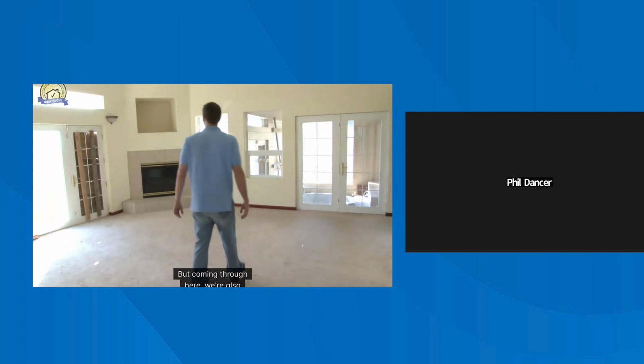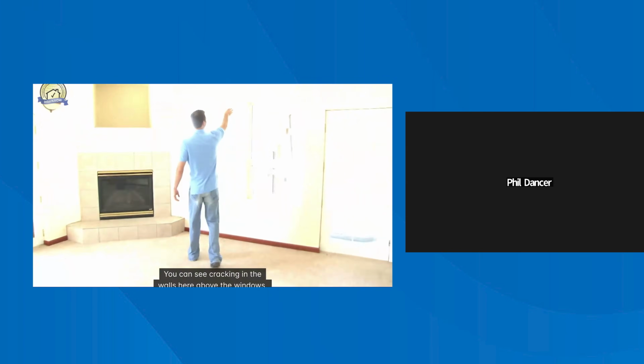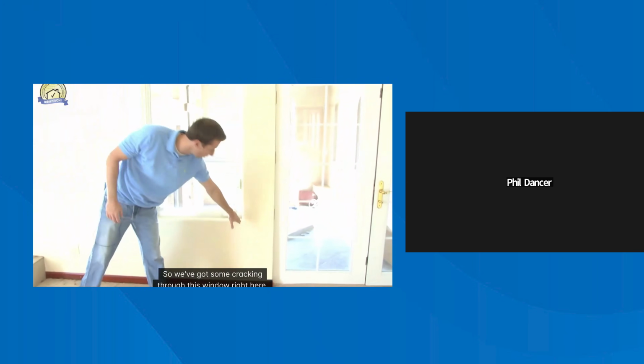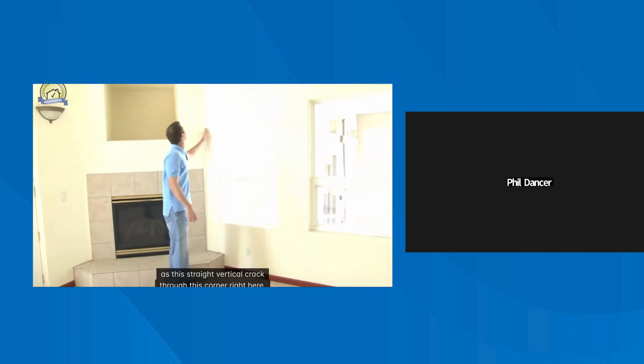Coming through here, we're also seeing more signs of vertical movement. You can see cracking in the walls above the windows. Again, windows and doors are the weakest points of a foundation, so it's the first place to look. We've got cracking through this window, indicating vertical movement, as well as a straight vertical crack through this corner.